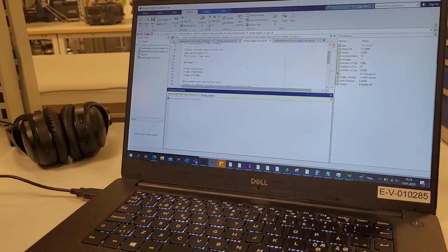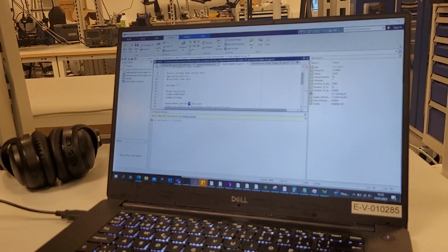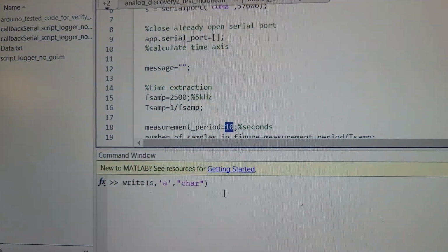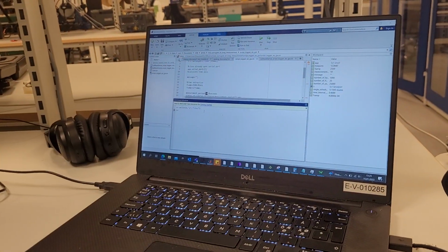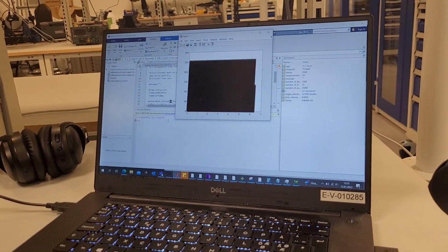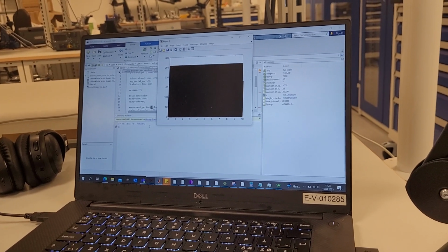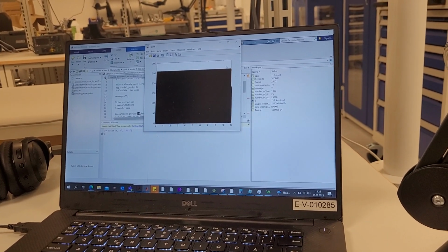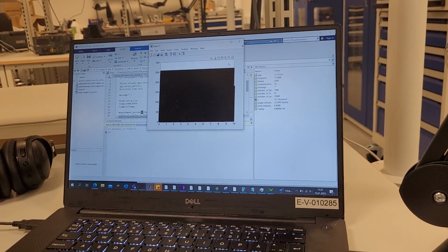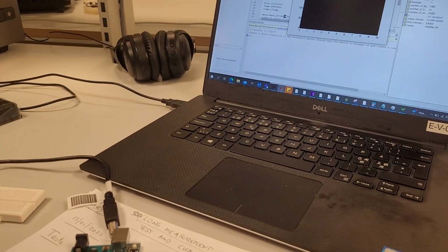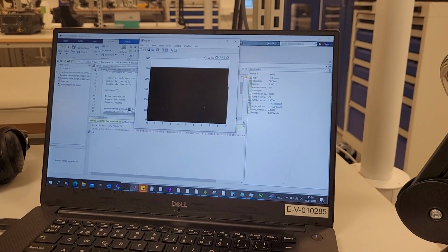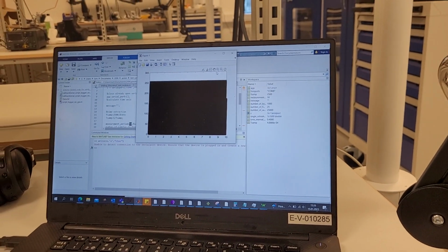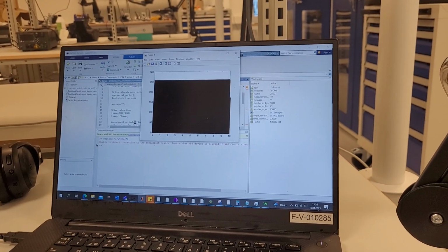The difference with the previous test is that now we select 10 seconds. Okay, I changed that from 2 to 10. Start again, and now it should acquire in theory until 10 seconds. Yeah, and then we stop. We disconnect it, because if we don't, then the data continues to be written to MATLAB, and the buffer of MATLAB can become so huge that it can make MATLAB crash.